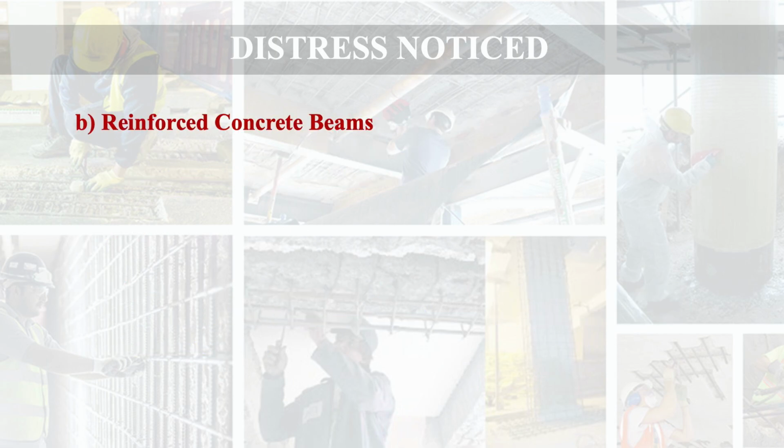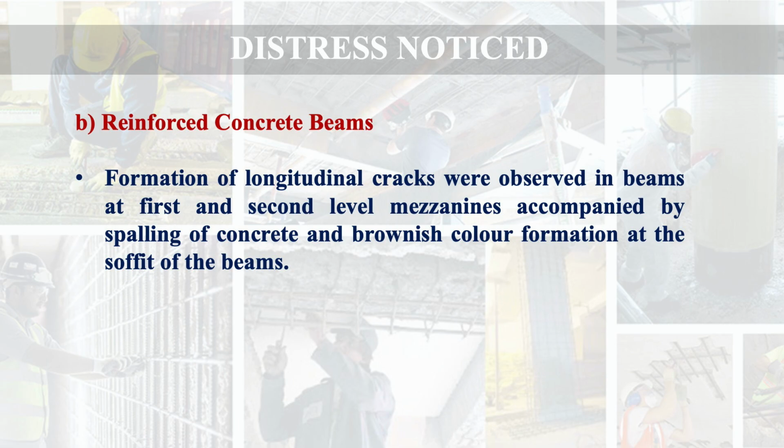In reinforced concrete beams, what happened there? Formation of longitudinal cracks was observed in beams at the first and second level mezzanines, accompanied by spalling of concrete and brownish color formation at the soffit of the beam.